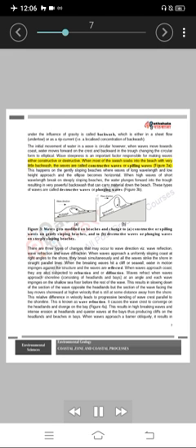When most of the swash soaks into the beach with very little backwash, the waves are called constructive waves or spilling waves, figure 3a. This happens on the gently sloping beaches where waves of long wavelength and low height approach and the ellipse becomes horizontal.